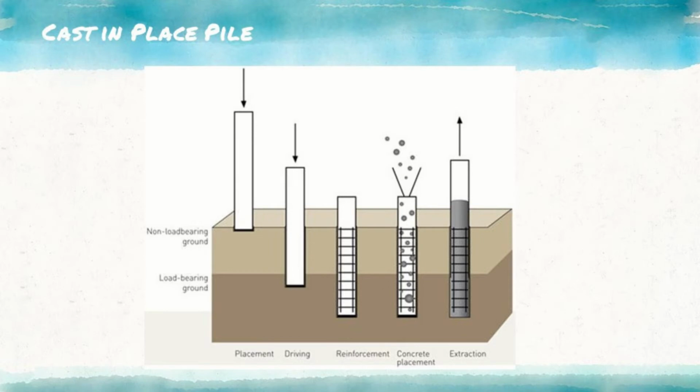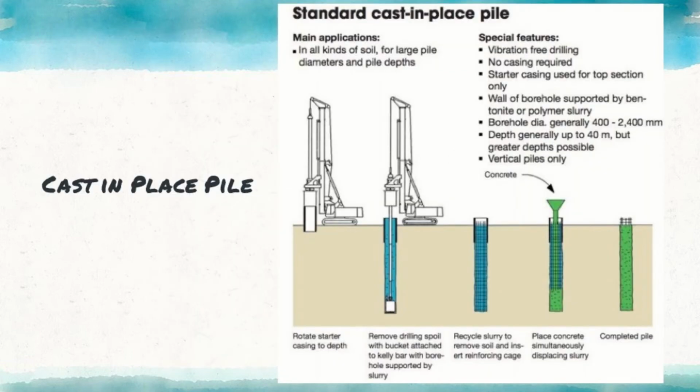3. Cast-in-place pile. This type of pile foundation is a foundation that is molded in place by making a hole in the ground first by drilling the soil, as in soil drilling during soil investigation. In cast-in-place, this can be done in two ways. 1. With a steel pipe that is driven into the ground, then filled with concrete and pounded while the pipe is pulled up. 2. With a steel pipe is thrown into the ground, then filled with concrete while the pipe remains in the ground.